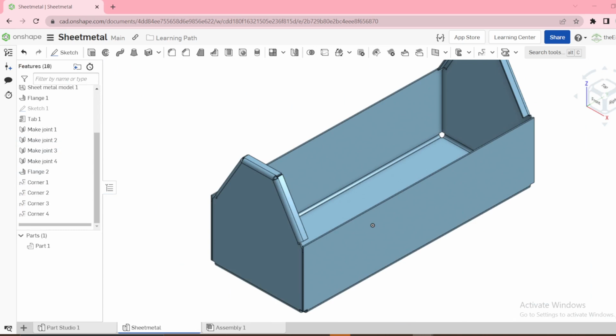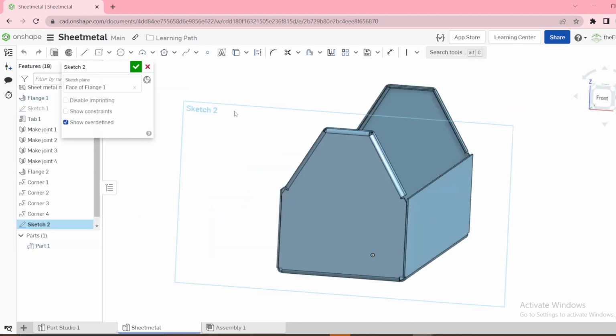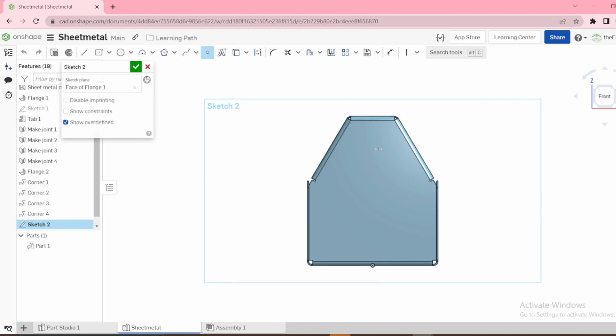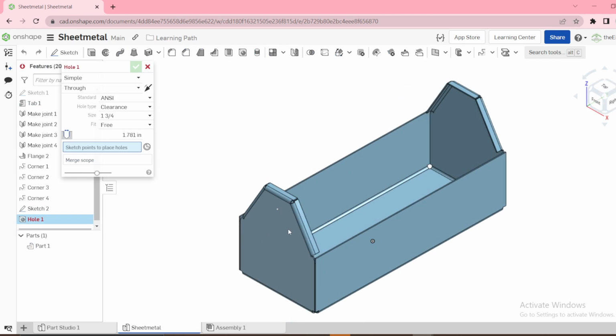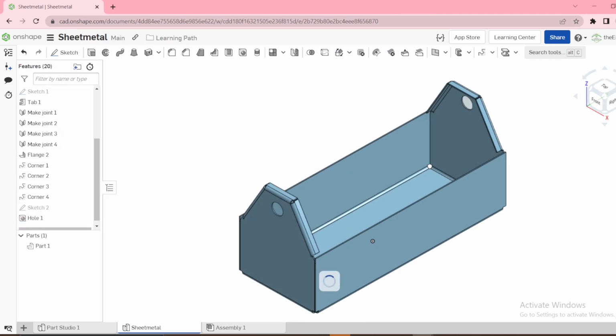Now we need to make a hole that is on this face that goes through. You can sketch on this face. Number two, you can put a point, by the way, like that. Dimension this to this point to be 12. That's all we need. Then use hole command and select this point. You can leave everything else default. That's our hole.